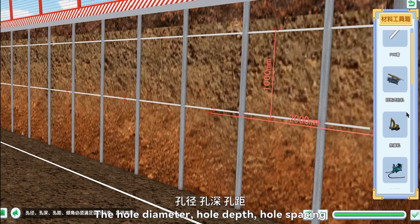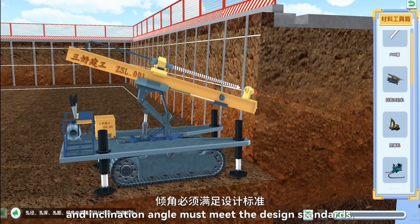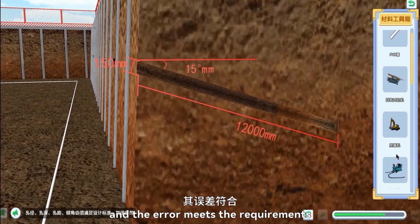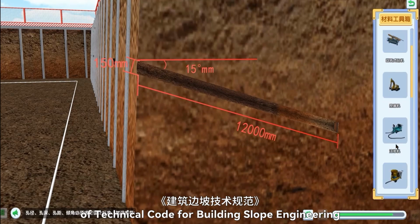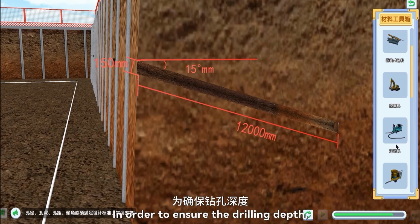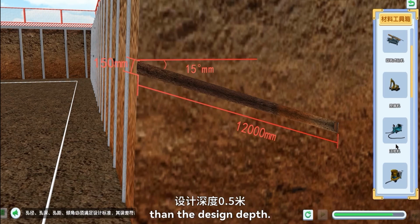The hole diameter, hole depth, hole spacing, and the inclination angle must meet the design standards, and the error meets the requirements of technical code for building slope engineering GB 50330-2002. In order to ensure the drilling depth, the actual drilling depth should be 0.5 meters greater than the design depth.